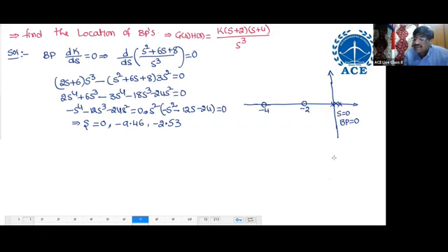So now tell, this is a breakpoint. Here, is there a root locus branch? No root locus branch here. Here, the root locus branch exists, because if you take a point, how many poles are to the right? 3 poles. 3 poles means root locus branches exist. Here, no root locus. Why? Count: 1, 2, 3, 4. 4 means even, no root locus.